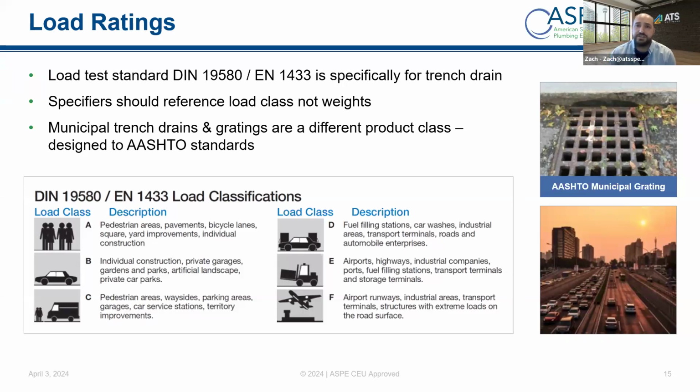So your location and design matters as much as the product itself, even when we're talking about trench drains. Yeah, I have seen trench drains right down the center of a warehouse. They had racking on either side, and the forklift driver, rather than turning as he's moving, his turning wheels would be right on the grate, and he'd be turning them, and they're kind of banging the grate up against the side of the channel.